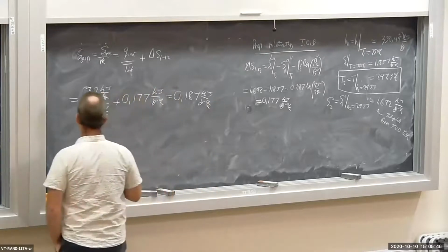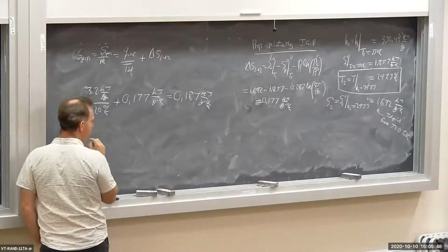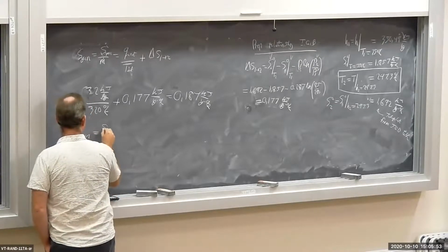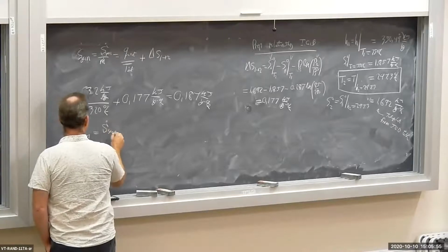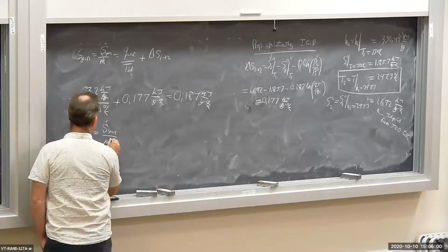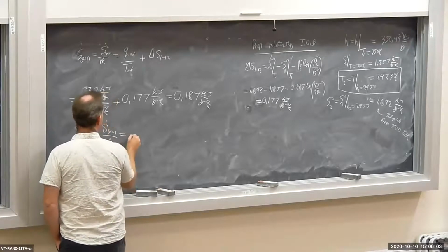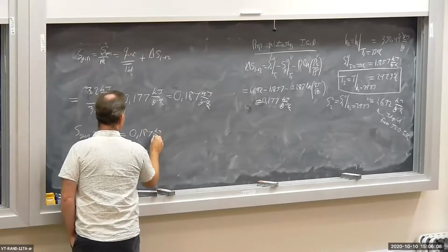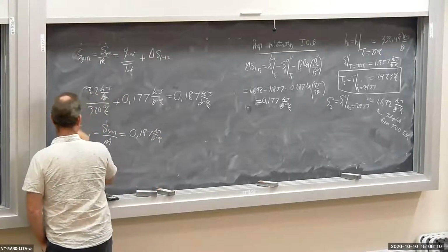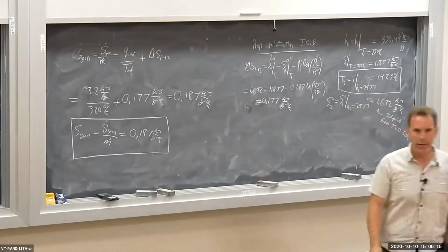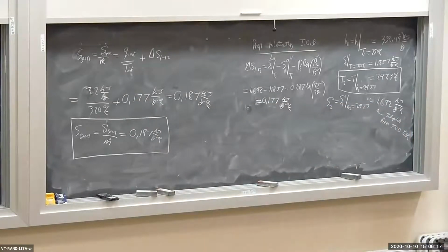So the rate of entropy generation per unit mass flow, S gen, which is the rate of entropy generation inside my nozzle, S dot gen per unit mass flow of air through my nozzle, is 0.187 kilojoule per kilogram degree Kelvin. Question, is this nozzle reversible or irreversible? It is irreversible. S dot gen is greater than 0.